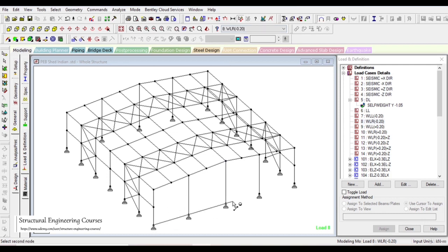this dimension is 18.5 and this dimension is 17.5. So obviously we do need to consider that in the case where wind is traveling from this point to this point, the loading shall be different, and from this point to this point the loading shall be different, because this length is different here. So this was the reason why I had shifted this 0.5 meter here, so that you can have a practical understanding of what if this portal and this length is unequal.